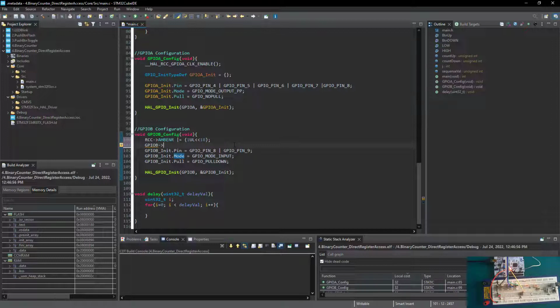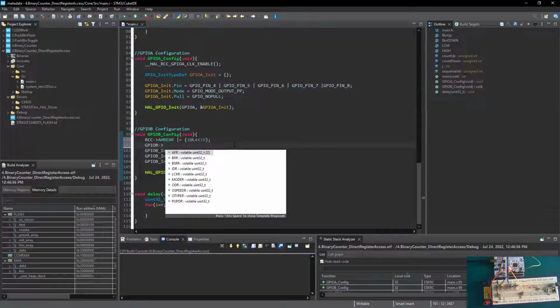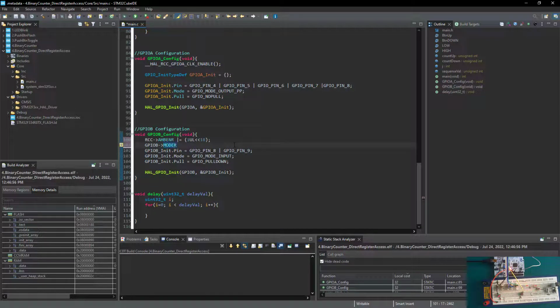And then I'm waiting for the IntelliSense to show me the options. There are the options. So the IntelliSense is telling me, here, this is what you have in this register. So I'm looking for the model. I'm taking the model, and in here, I'm just going to say I only want to write zeros on all of them. So I'm just going to write 0 like that. Hexadecimal, binary, decimal, it doesn't matter. It's still going to be just 0. Okay, so I don't need this. I can already remove it.